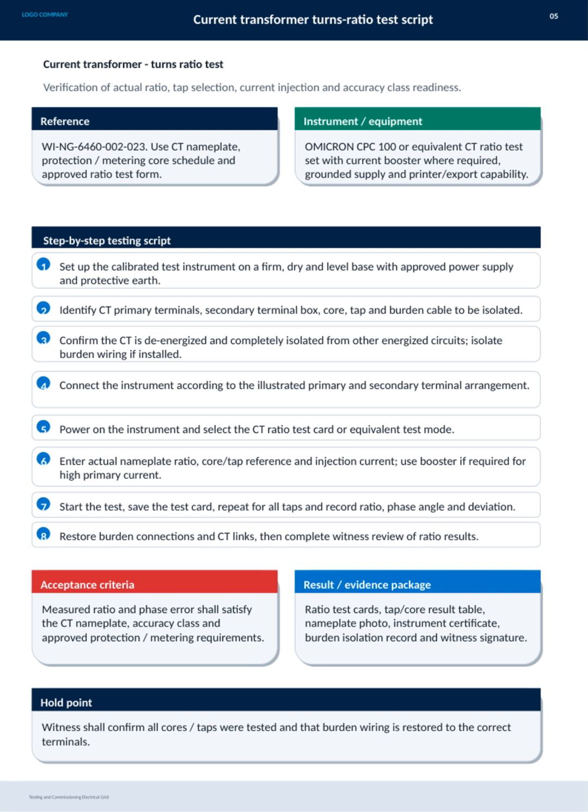Lastly, a critical hold point is that the witness must confirm all cores and taps have been tested and that the burden wiring has been correctly restored before proceeding. This ensures the reliability and accuracy of the current transformer's performance.